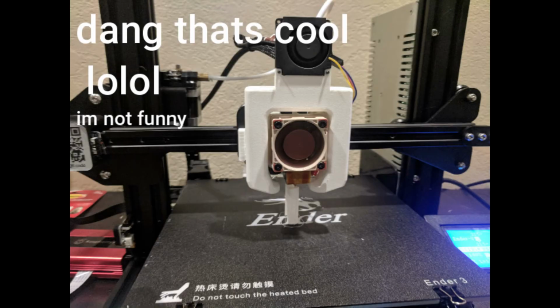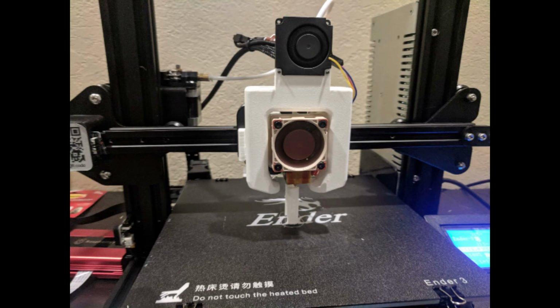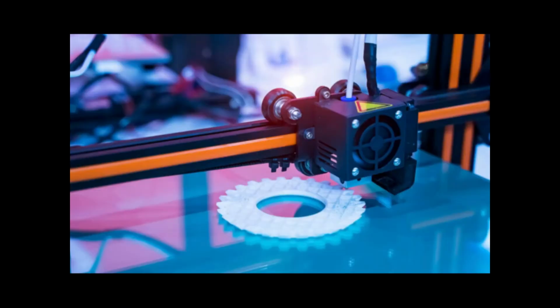I also changed the fans on my 3D printer. I added silent Noctua fans, which keeps the 3D printer from being loud at night. And I also added a blower fan. This allows the tool head to be able to cool the filament as soon as it comes out of the hot end. This allows the 3D printer to have better bridging, which is 3D printing in the air, and also allows the 3D printer to print at a faster rate.